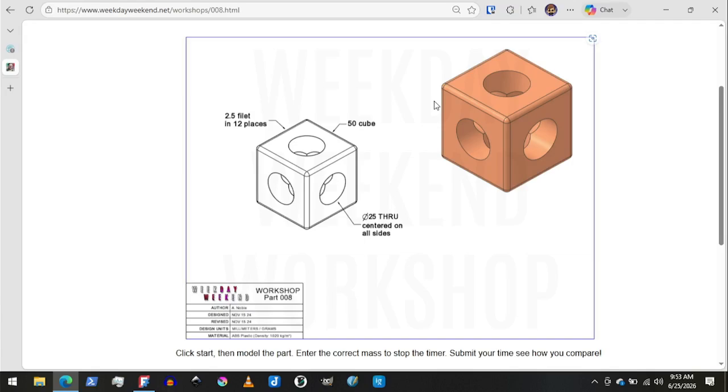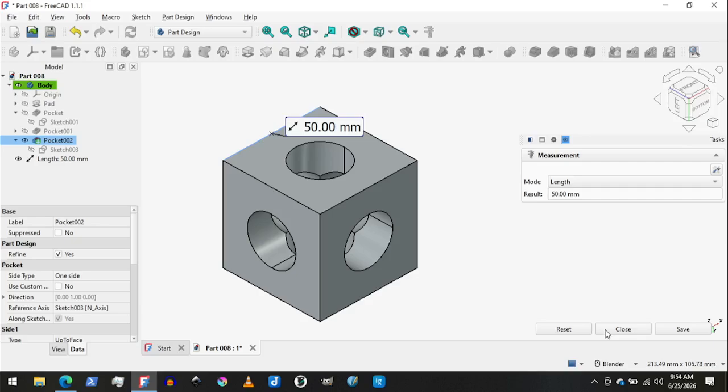So what I could do in FreeCAD is take this measurement and start to design a replica of a real object. Let's say a part on my bicycle, and I want to make a replacement. I take my calipers and measure the bike frame where I need to build that replacement part, and I get those measurements. I always recommend writing them down so you don't have to go back constantly. I write them down on my computer and build a replacement based on my real-world measurements. So if you get yourself a pair of calipers.